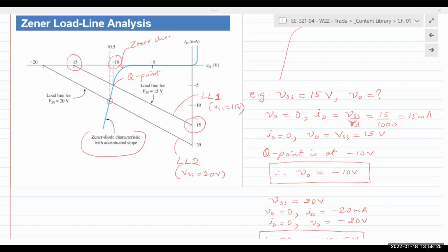So we can check our capacitors within that circuit to provide voltage that's constantly above it. Yes. So anytime we want, let's say, an output for a USB port, our USB chargers need an output of 5 volts. So the filtered output that comes in is much larger than 5 volts.